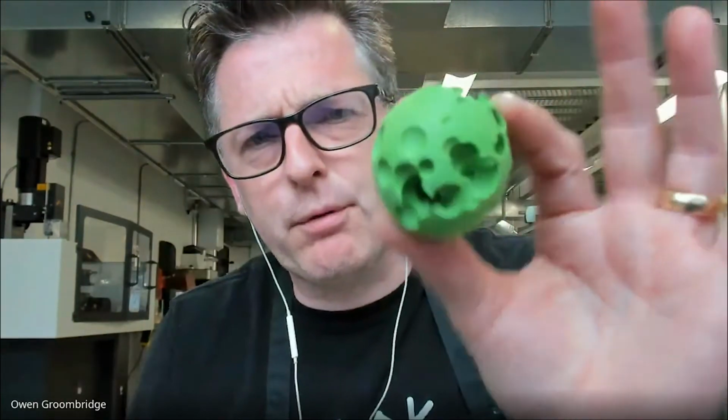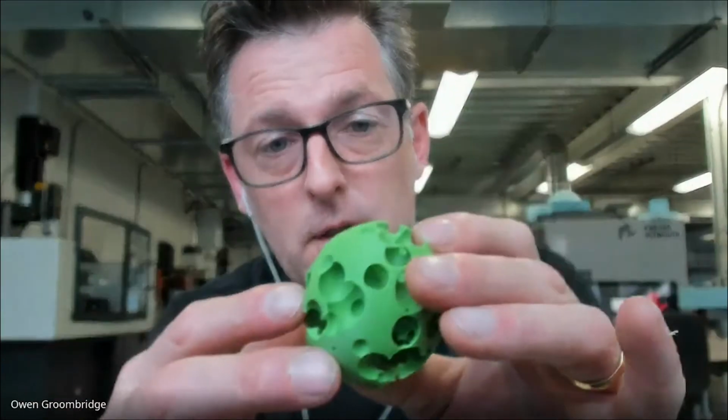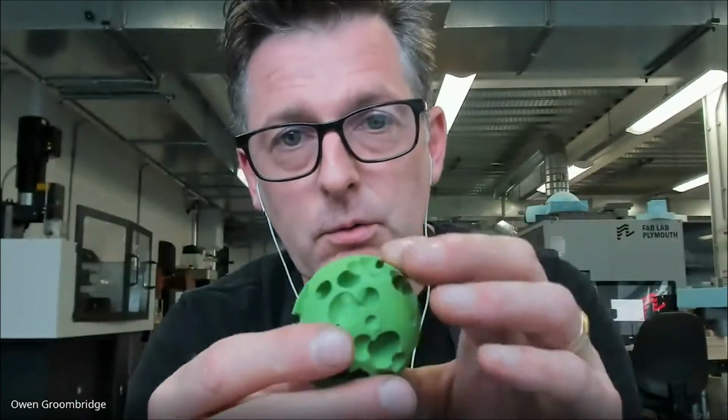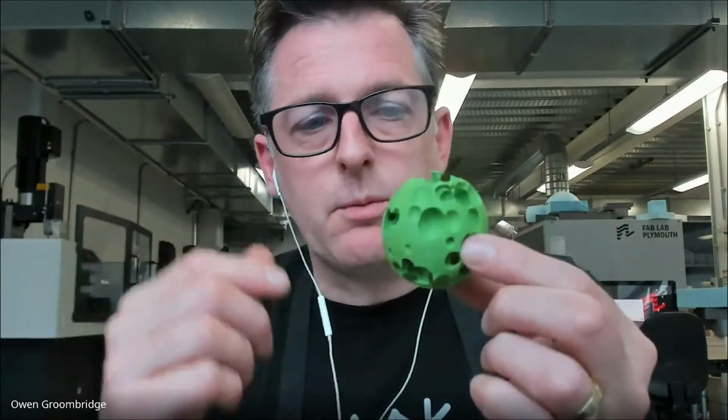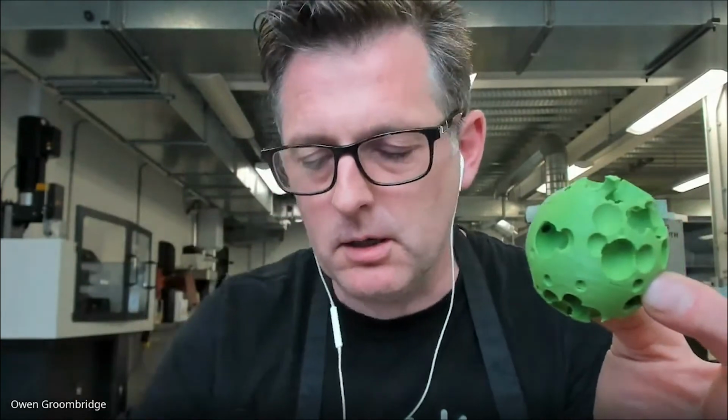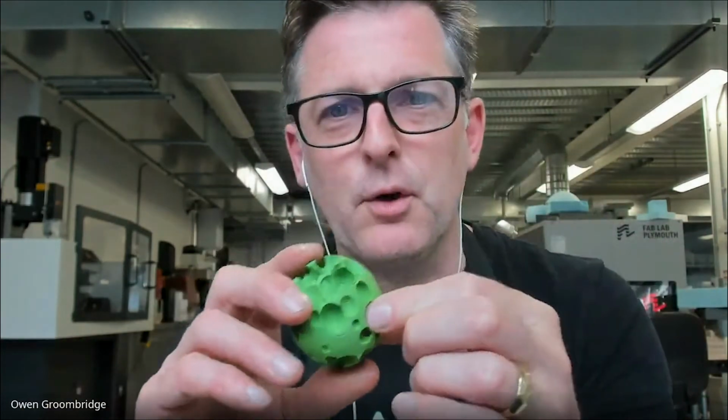This was made on a printer that has a dissolvable filament. All the support material, we've dissolved away in water. It's important to understand that the reason you have to have support material is because you can't print in thin air. It's got to have something under it. So in that sense, this is not truly 3D, it's 2.5D. It's an unusual one, 2.5D.